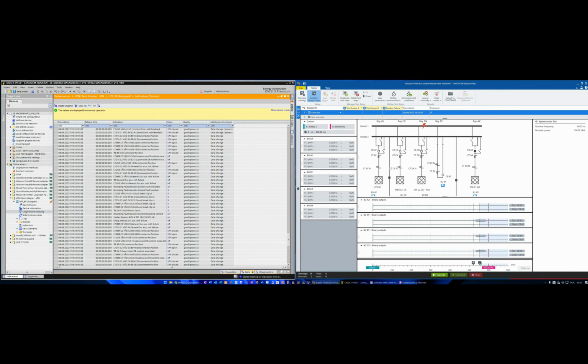And here, this is all the events that we have in the relay. For example, I applied a fault here at this time, 500. So here, in relative time, you can see it's 0. So if I go through this, for example, we can see that we have a bus bar protection check zone.